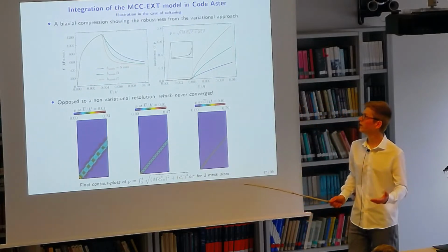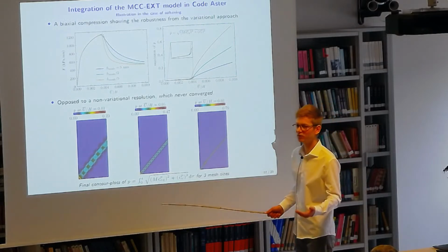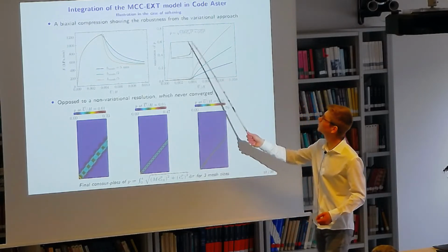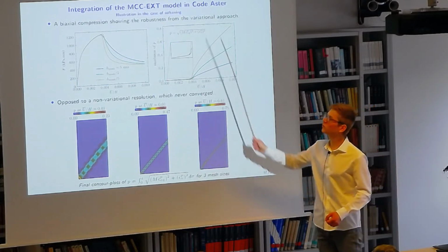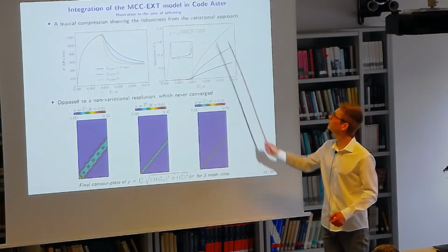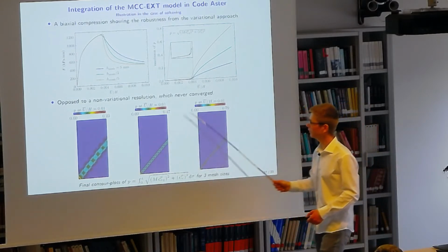However, you can also observe that up to now we have not solved the issue of mesh dependency, since, for instance, a cumulative plastic strain, which takes into account by a quadratic interaction the deviatoric part of the plastic strain and the volumetric one, depends on the mesh size used, as you can here and there observe.